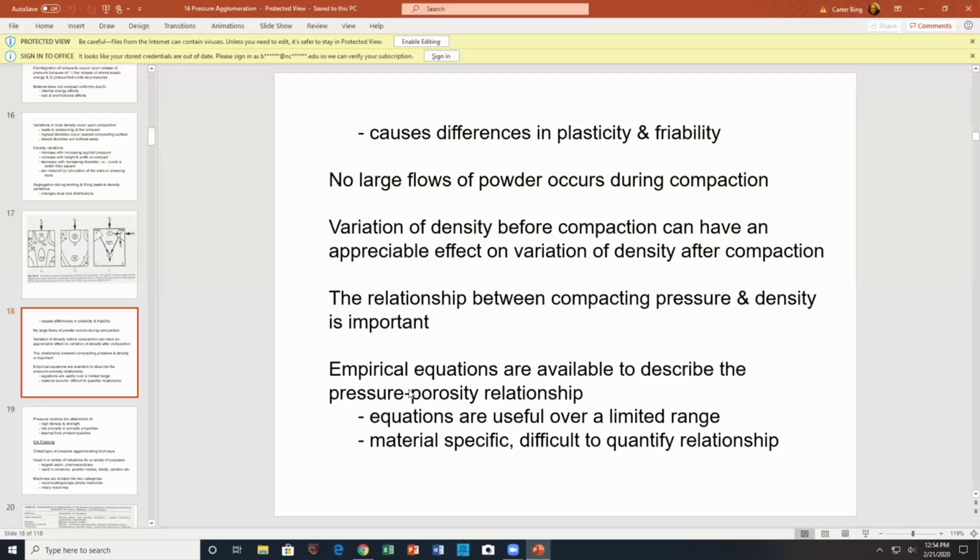So what you might do is take one of your tablets, one of your pellets or whatever, your agglomerate, and sand it down or remove different layers, photograph it, remove another layer, photograph it, remove another layer, photograph it, and then play the photographs of all 70 or 80 photographs you've taken as a continuous video.